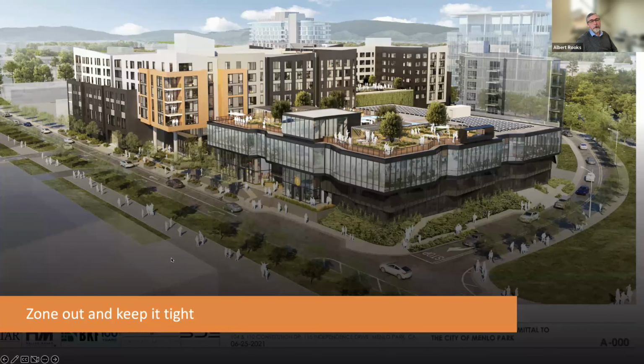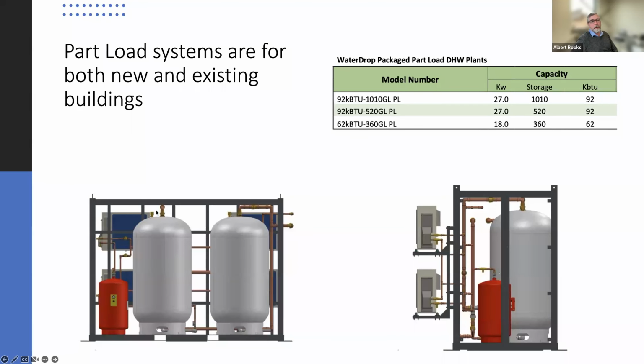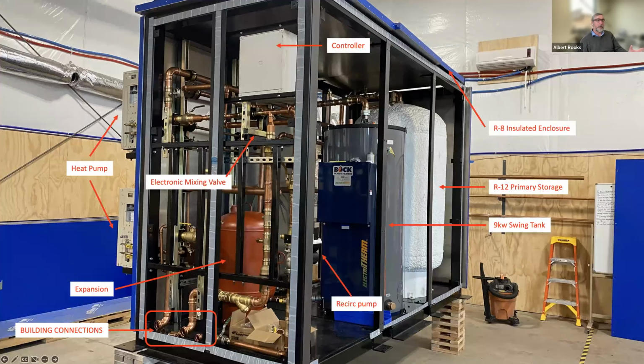So if we go back and look at this one, I was going to jump a couple back, right? The whole thing's wrapped in an R8 enclosure with continuous insulation. And because I'm designing it, the insulation is natural cork insulation, R4 per inch. It's got some nice density to it, and I'm just not a great plastic foam fan.